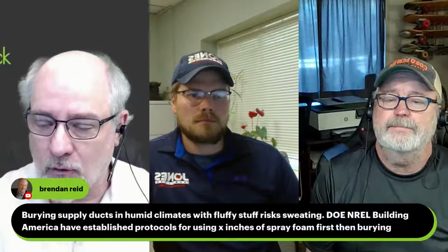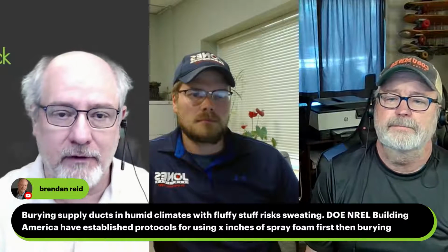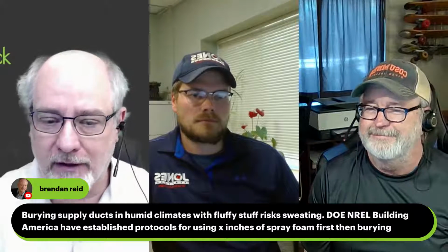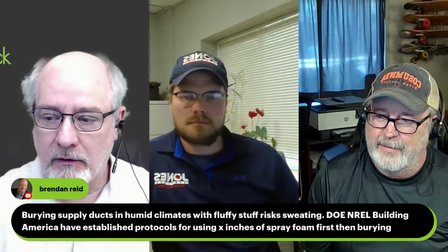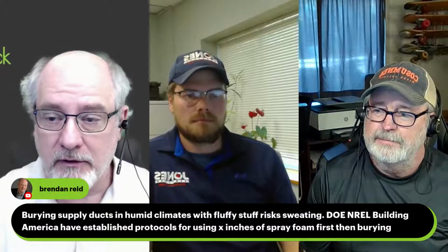But yeah, we have a couple of comments. Brendan Reed, thank you. I haven't seen you in a long time. Hopefully you're doing well. He had a whole thing about burying ducts. There's actually a variety of requirements or guidelines about how to do that, especially in the South, where you may end up with sweating and condensation that shows up, and you don't know it because you can't see them anymore. Well, I lived in Georgia for quite a while, and they do such an amazing job of trying to insulate their ducts, whether it's a crawl space or even attic, that they actually increase their air sealing, how tight the ducts are, because of how well they insulate. Sometimes the ducts can be leaky, but it all stays inside their insulation. It may not get out of your supply register, but they still do a good job.